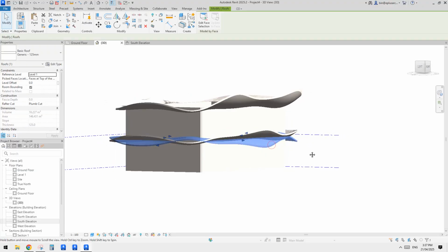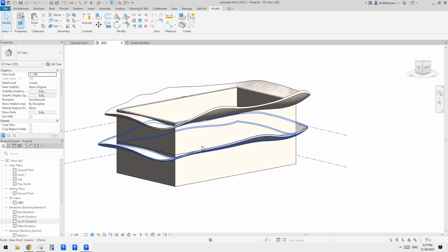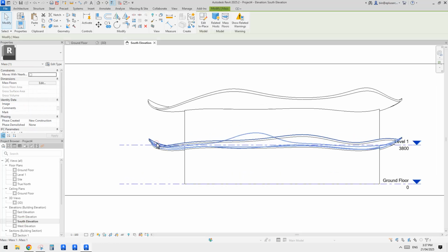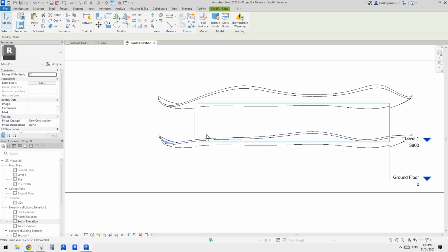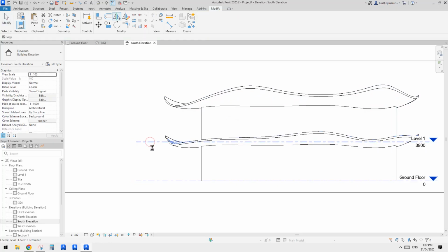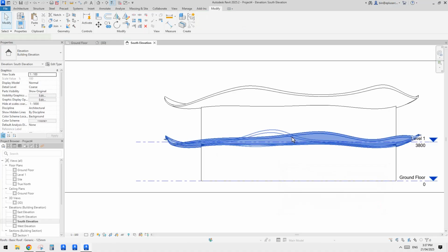And then you probably just want to adjust. Oh, hang on, did I just maybe mirror the roof? No, I probably. Yeah, we should mirror the mass instead, because if you mirror the roof, you will never be able to change the shape of the roof. But if we mirror the mass, doesn't work. Okay, yeah, it looks like it doesn't work.